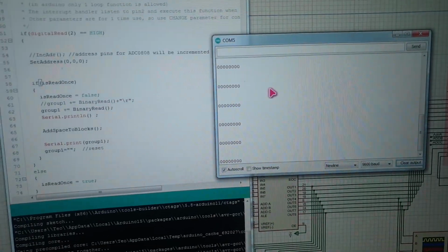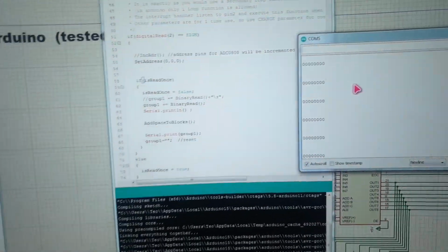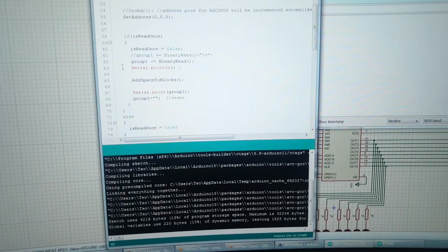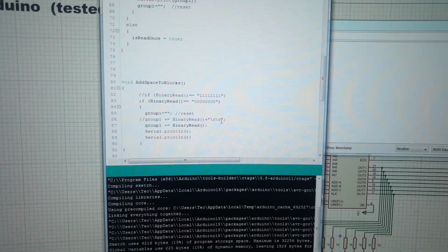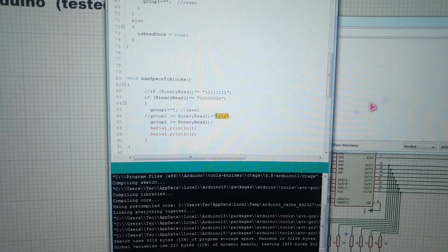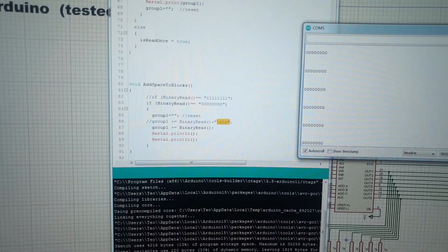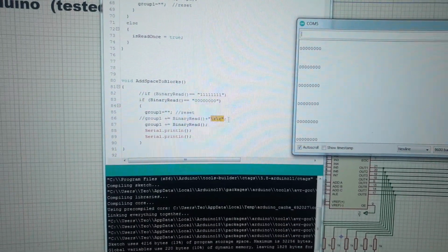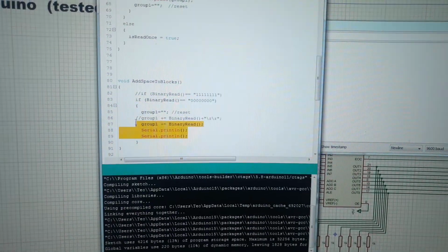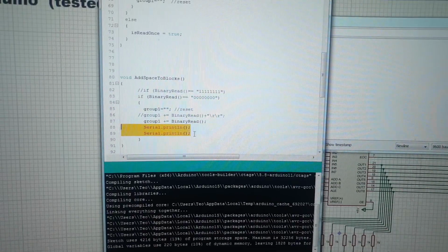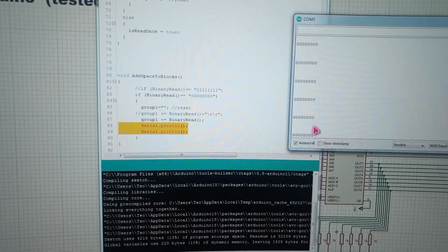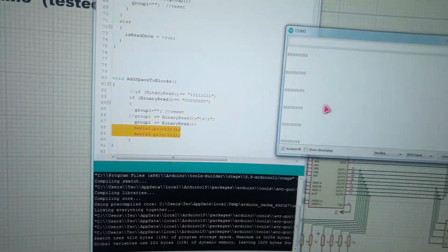And if it's reaching that 0, it's giving me a double new line. By the way, my friend from England was complaining about this in his code. It didn't work with \r. You see this \r and the other \r, this double \r. It didn't work with COM5 here, with this serial monitor. For this to work, I commented this out, and I made it like this with the serial println methods that I'm having here to actually show one on top of the other in the serial monitor. And he was having this problem.